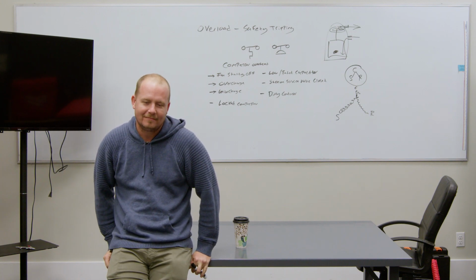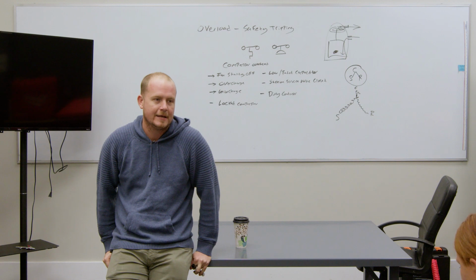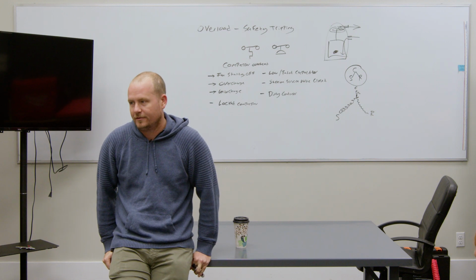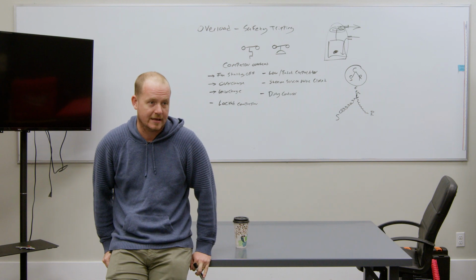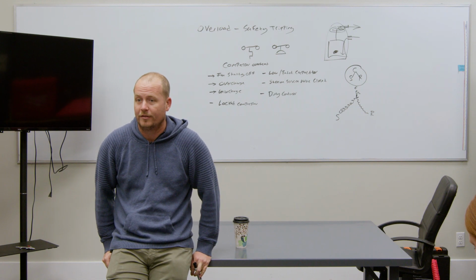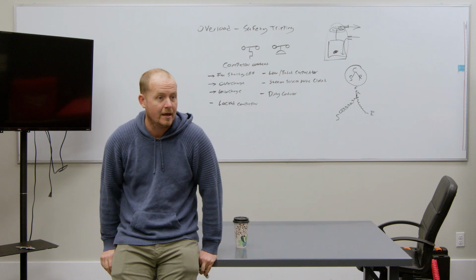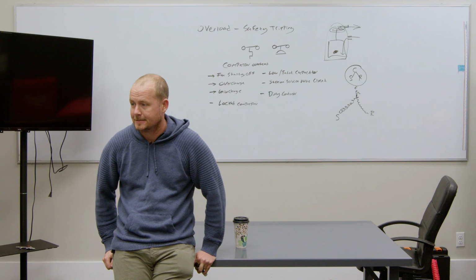All right. So the message is, anytime you have an open thermal, anytime you have an open safety, find the reason why it opened. Don't just believe in magic that it opened, because sometimes they just open, they can fail for other reasons, things can happen, but when they fail because they've been opening and closing, safeties ain't supposed to open and close. Make sense? Right. Great. Have a wonderful week.